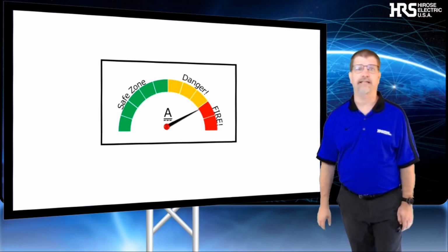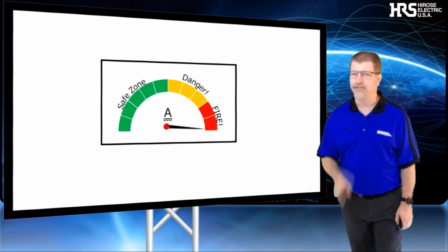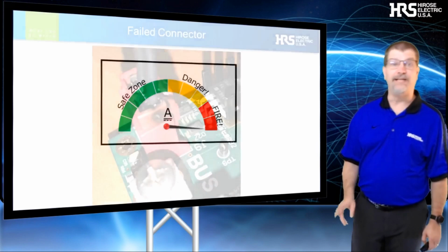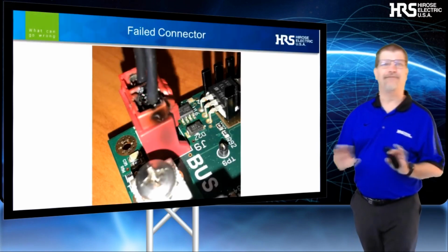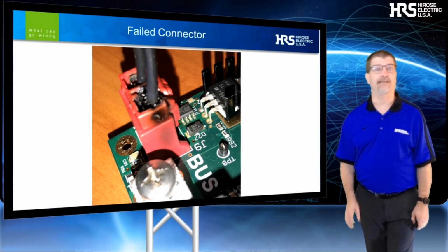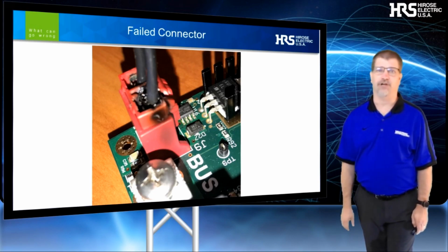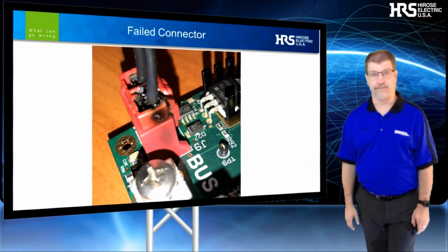As that contact heats up, yes, we know that will produce a higher resistance value, but the core problem still exists, and we need to be mindful of it. We never want an overheating contact. Connector and system failures become a real possibility in this situation. This brings us around to talking about the derating of connectors.